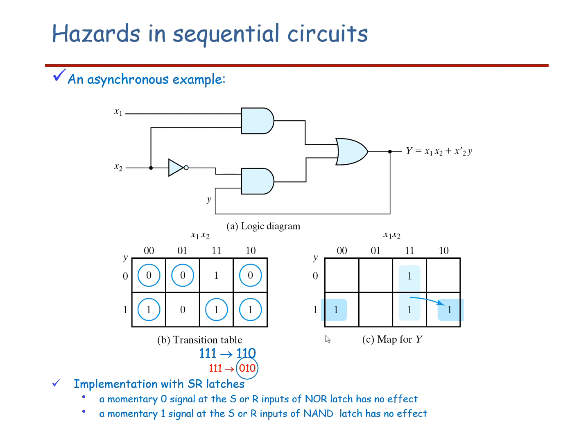Next, we will move on to the hazards in your sequential circuits, especially in asynchronous sequential circuits. In the previous video, we discussed how hazards occur. There is a static 1 hazard, static 0 hazard, and dynamic hazard. There is one more hazard, the essential hazard, which we also discussed in the previous class. It exists in asynchronous sequential circuits, where there is a feedback, and here we are going to consider the essential hazards and how they can be overcome.